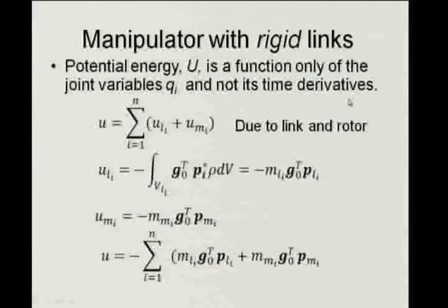We take two components, link and the motors, separately, and find the potential energy. That is very simple, we just find the vertical height and multiply it by g, and that term will land up here. It is no big deal, fairly simple, and you already know how to do forward kinematics. So writing in terms of q is not a problem.